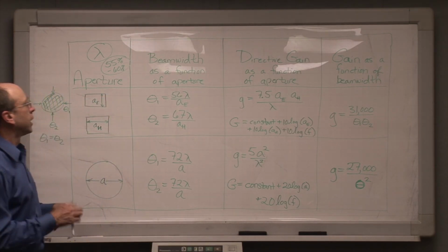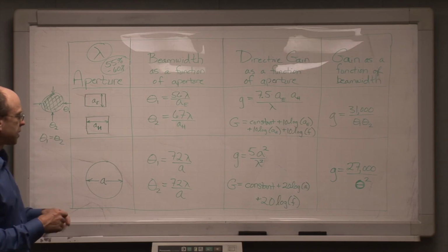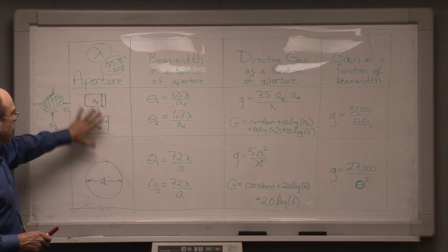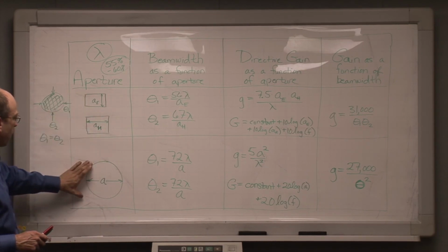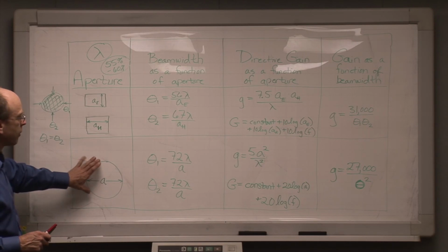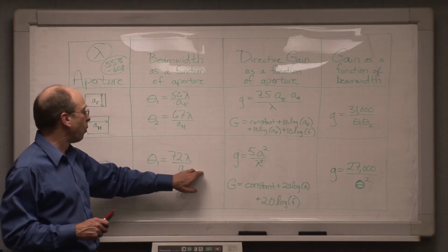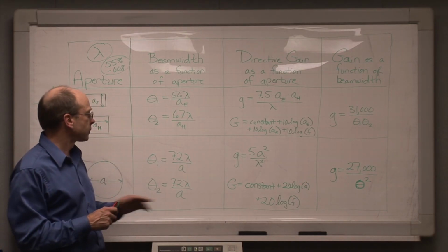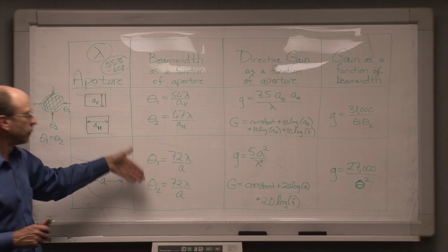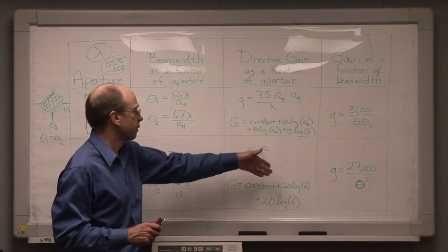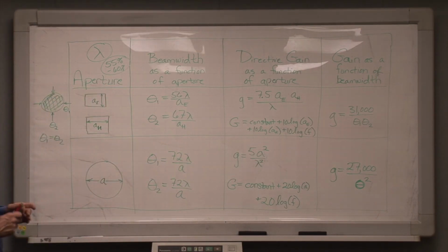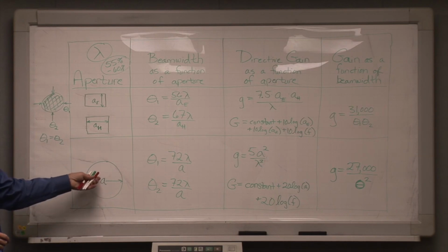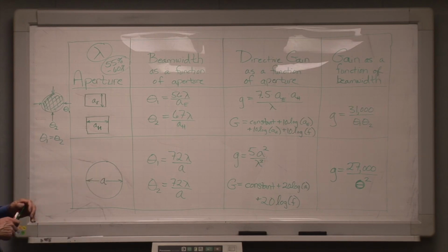And that basically concludes the talk. Anytime that you see an antenna, either a horn antenna or a parabolic dish antenna or even a radar antenna that's a sort of cosecant squared, you can roughly calculate the gain if you know what wavelength it's working at, or you can work the relationship backward if you know the wavelength but you don't know the gain. You need to know one or the other, but if you know one, you can back calculate the other one. This also explains why we don't typically build dish antennas to operate at 10 megahertz.